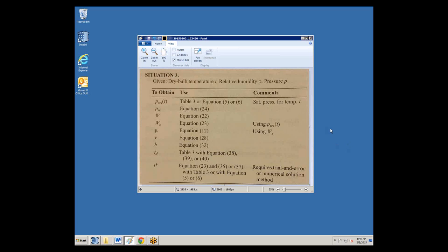In the 2013 ASHRAE Fundamentals book, you can see a section on calculating the wet bulb temperature, given the dry bulb temperature, the relative humidity, and the pressure. We have dry bulb temperature and relative humidity that we read, as I'm sure most of you have the same thing, and you probably already have calculations for either enthalpy or wet bulb that you use for determining when to go into a free cooling mode.